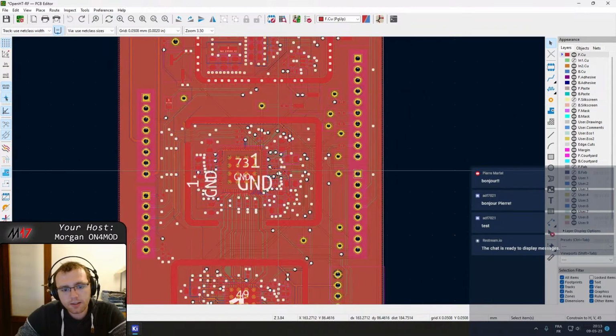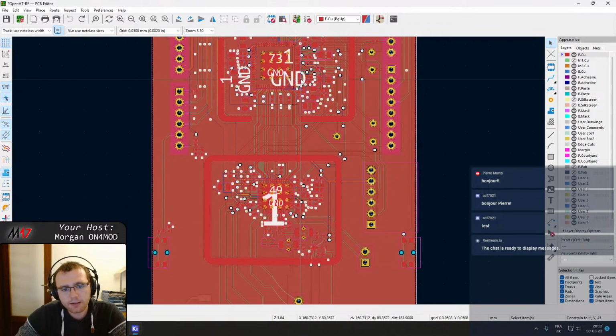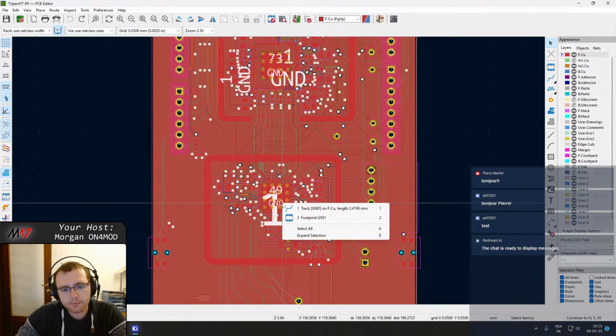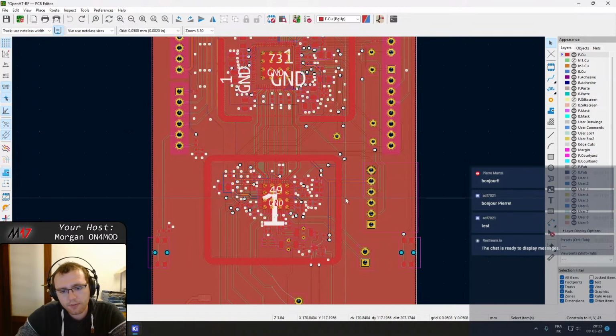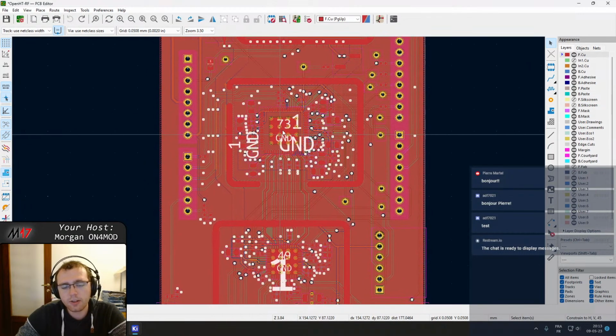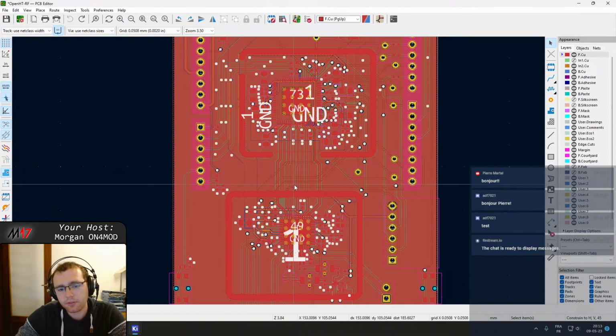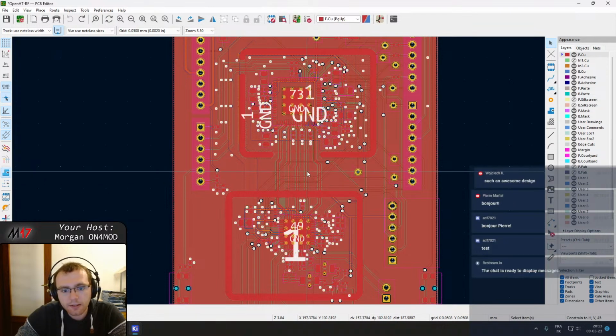Mainly, I think one of the main things is that the transceiver has moved a bit to the left, so that we have room here to place the shield, and it's more aligned with the FPGA for the differential pairs of the LVDS transmission lines.